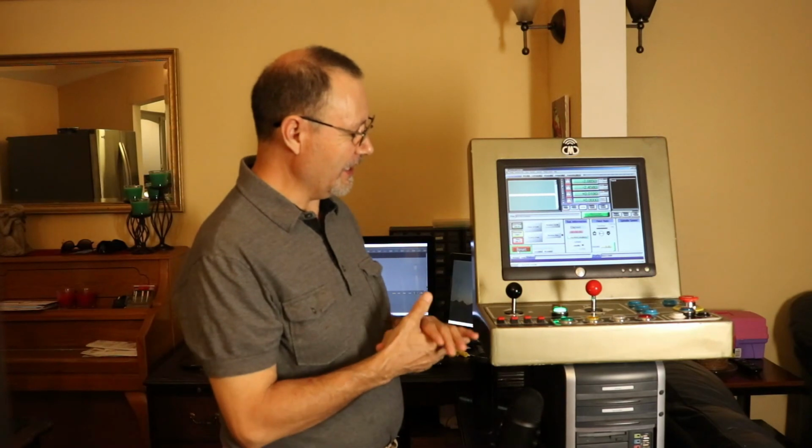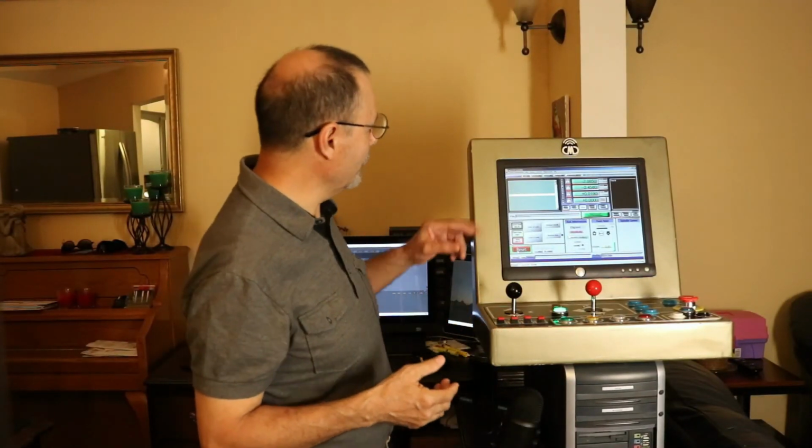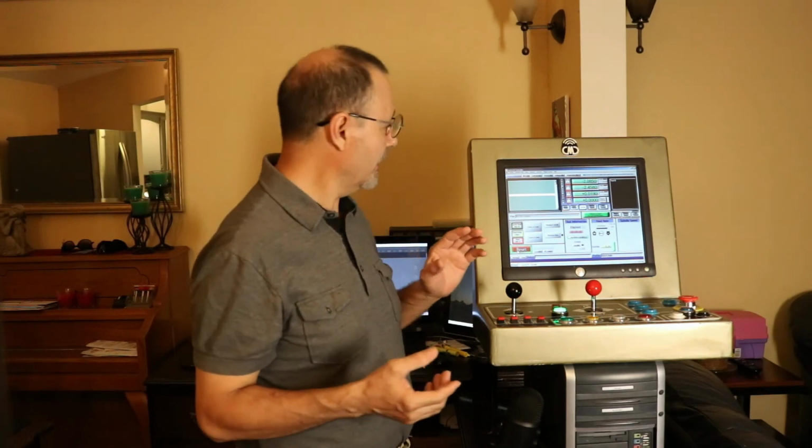As you can see, it is possible to make the buttons illuminate, providing that you write a brain for your applications or whatever function you're trying to implement on your machine. The good thing about running a brain is that it'll run in the background. All you gotta do is go to Configure, Save Settings, and then go to View, say Current Configuration, and the next time you start Mach 3, the brain will automatically be loaded into the program.